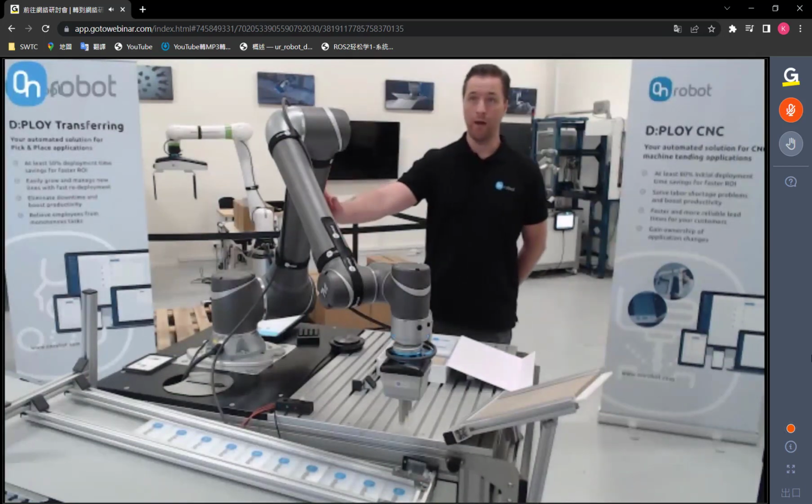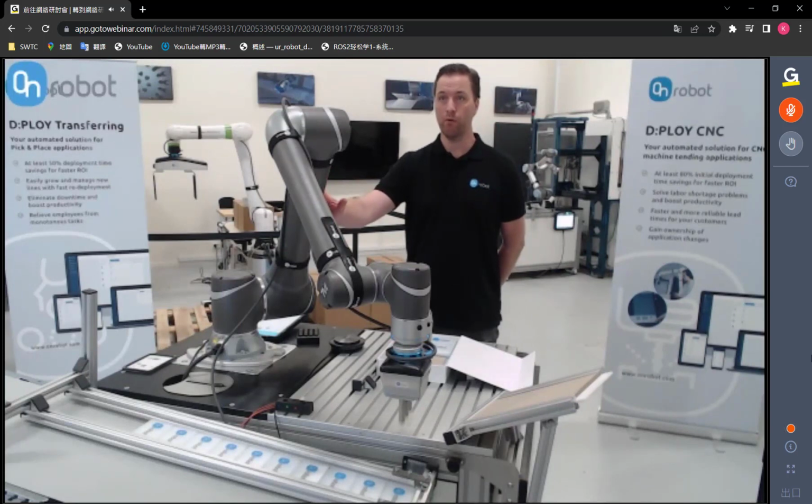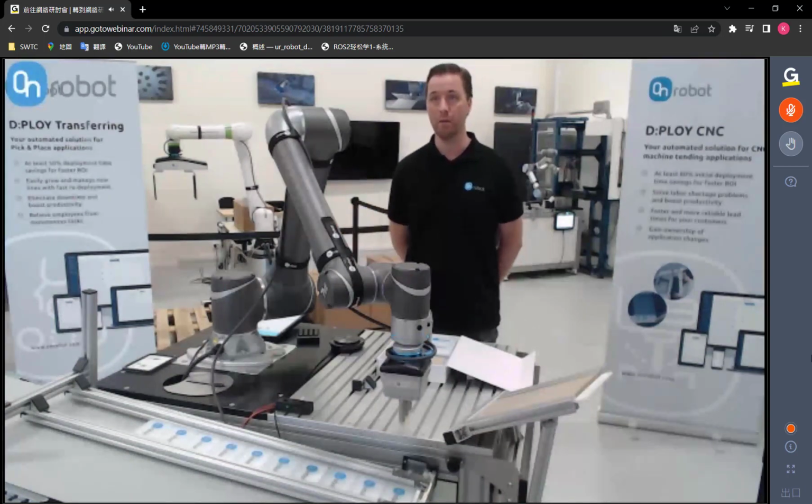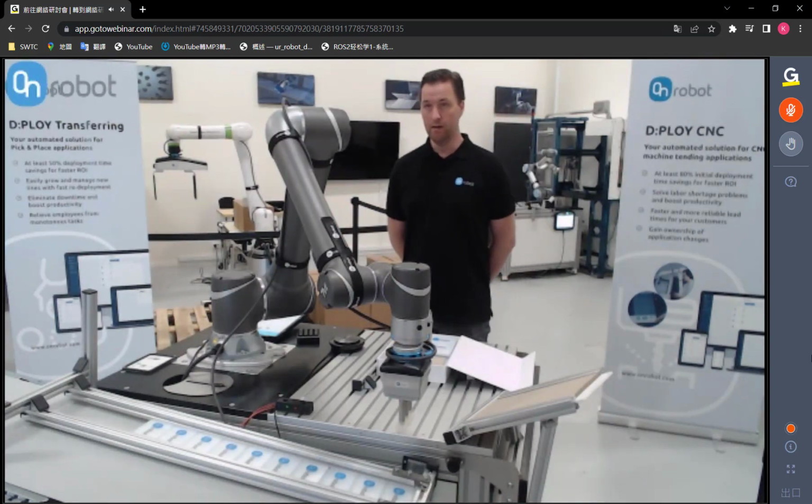The Techman robot that we have here needs a very small program. You make a listen node that listens to itself and start it as an automatic program on the Techman. Once that is done, you don't need the teach pendant anymore. For some of the other robots, it's even more simple.